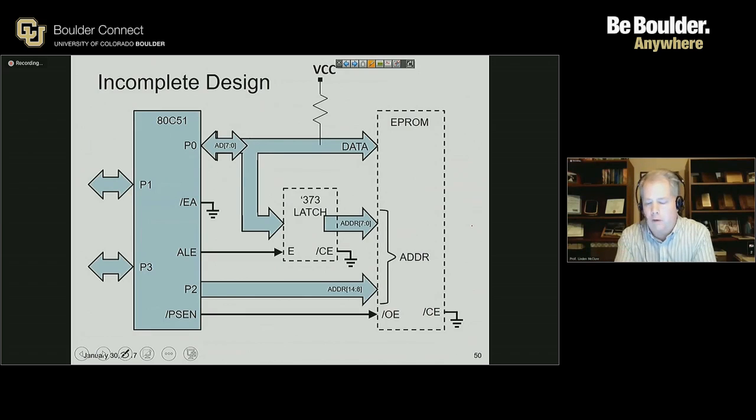And what this diagram is showing is that the code storage device, called EEPROM here in this diagram, but could be an NVS RAM, could be any other type of code storage device, is not currently present. I've got the dashed lines around it. The processor then has basically some lines that are connected to the board, but not connected to any other integrated circuits on the board.